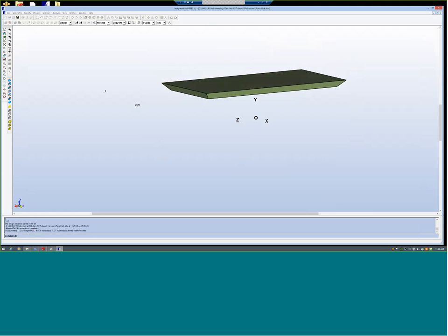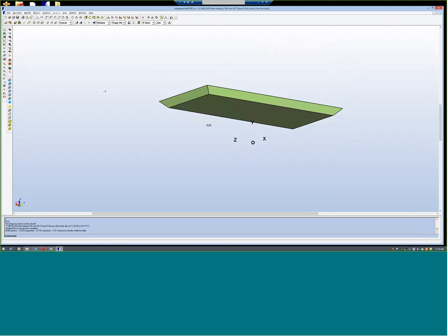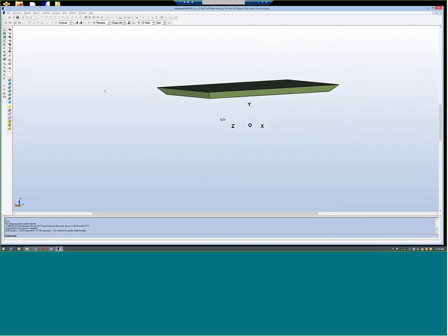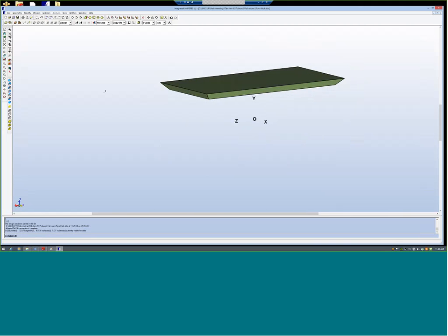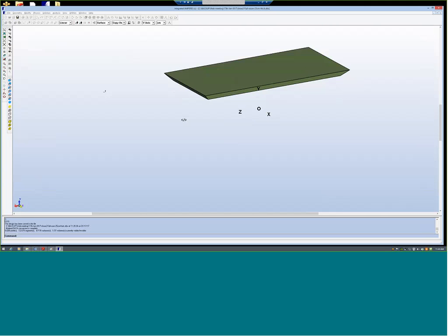You see here in this top volume, it has 6 surfaces: bottom one, top one, and 4 side surfaces. The 4 side surfaces don't need surface elements, because they are interfaces between the same type of material, the 1010 steel. So you don't have to assign the 2D mesh. What I do is I will hide even those surfaces also. This surface, hide it.